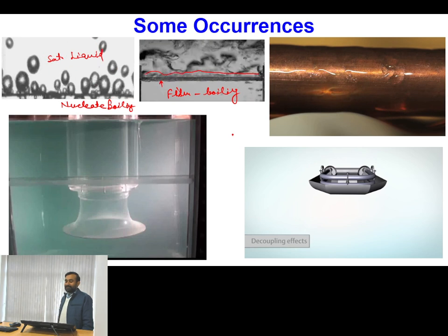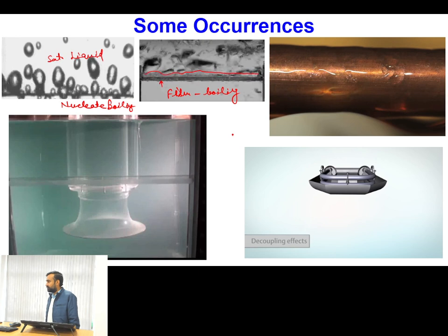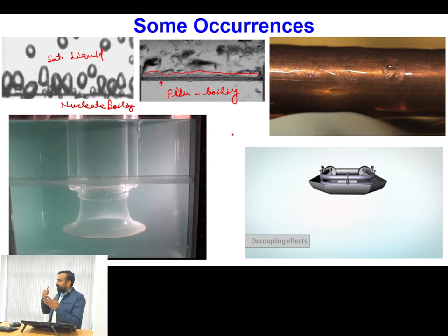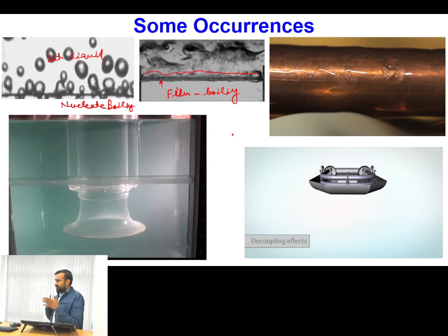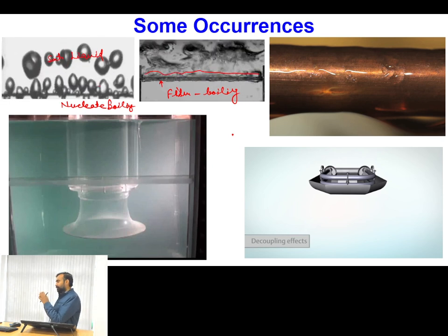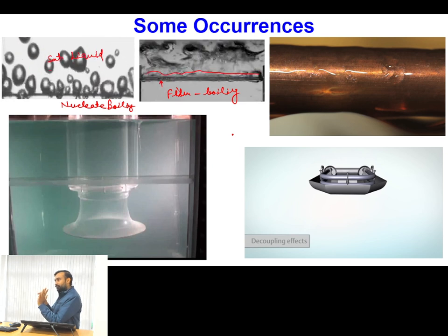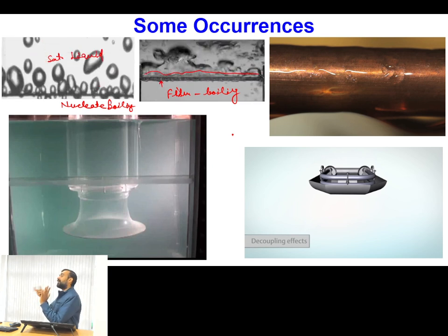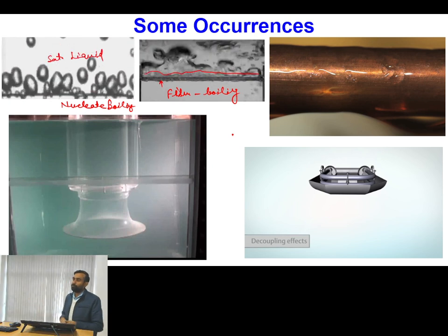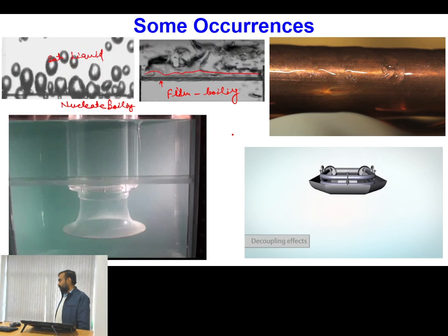However, for achieving the high heat transfer rate, the desired phenomena is drop-wise condensation, because in drop-wise condensation, vapor is directly contacting the solid surface and transferring the heat. In case of film-wise condensation, in between the vapor and the solid surface, there is a thin liquid film, and the additional thermal resistance of the liquid film comes into picture, because of which heat transfer coefficients in film-wise condensation are significantly less in comparison to drop-wise condensation.